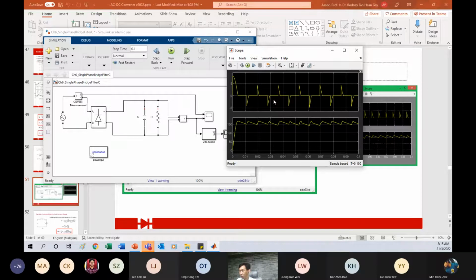I'm not sure until you do the measurement on the harmonic currents. Secondly, harmonics are somehow, directly or indirectly, related to power factor. Because the input is a sine wave, you no longer have the same in-phase current and voltage. Because of that, it will also introduce a power factor problem.